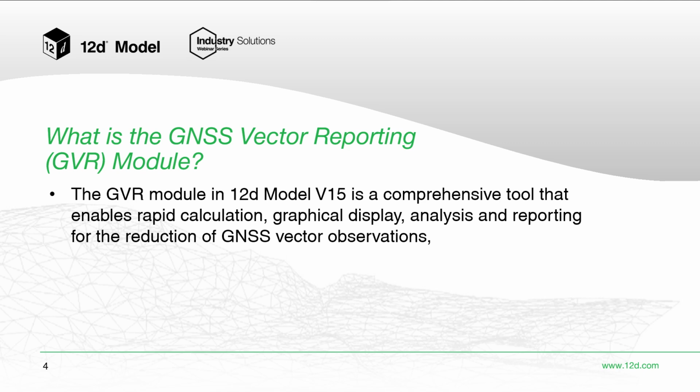Now, it is a module designed for cadastral surveyors, but it's not limited to that. So if you do GNSS surveys and you want an effective tool to reduce all the information from the field, can be for set out, control surveys, what have you, GVR module is for you.